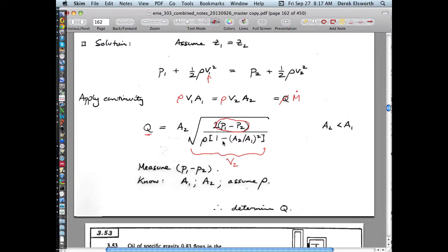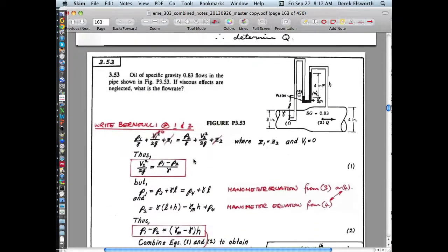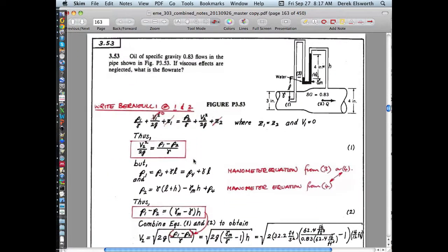And so you can measure it with a differential pressure transducer, which measures just the difference in two pressures at two out ports in the system. Or you can measure it in terms of using manometers. And so there the system is roughly the same. You could measure the behavior upstream and downstream of the constriction, whatever that constriction is. Or you could measure them in some complicated way like this one.